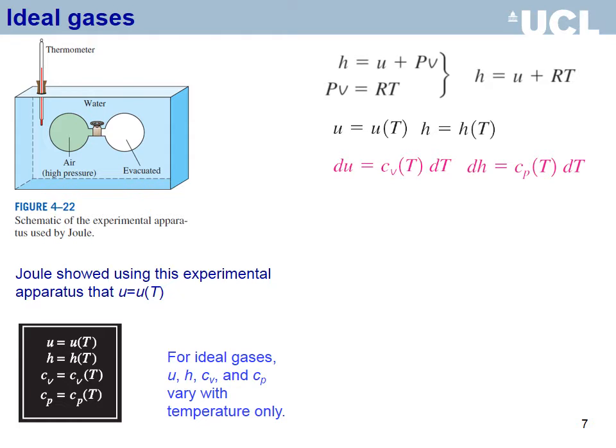For ideal gases, there is a very unique characteristic that Cp and Cv have, and that is that they are only functions of temperature. In general, we know from our first few lectures that a property should depend on two different independent properties. But that's not always true.